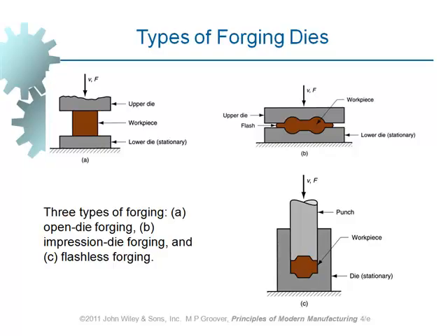What are the 2 roles that flash plays? If the flash is in here, because there is friction between the surface of the flash and also the surface of the die, it does act as a barrier against the flow of the material. It acts as a brake. So the material cannot flow along this direction and the other direction, and is forced to fill in the cavity of the die instead of flowing.